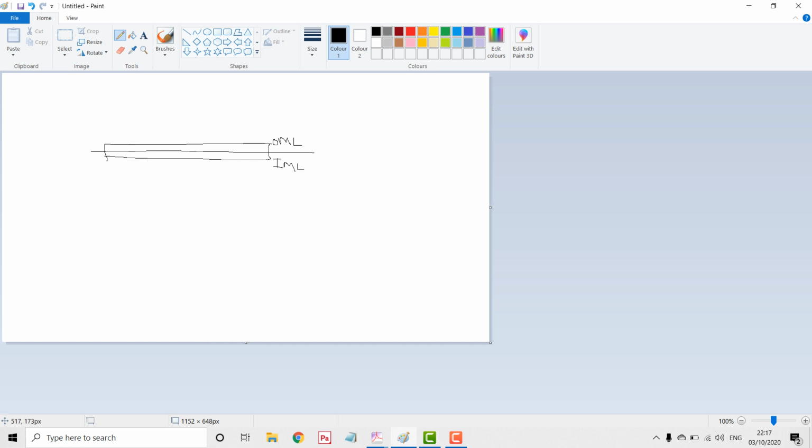Based on whatever the user selects based on engineering judgment, you have to be really careful with the modeling philosophy in terms of assigning the offset. Whenever the mesh is done on either OML or IML, you need to specify the element offset so that it exactly captures the boundary.